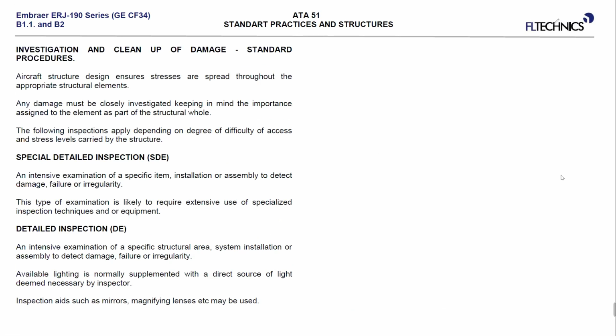So they put in the book, aircraft was hit by the bridge, everything is fine, aircraft released with small dents. Okay, no SRM reference, no dimensions of the dents, no location of the dents, on which frame, on which stringer, nothing. So they released the aircraft without any number. Okay, this is absolutely not professional.